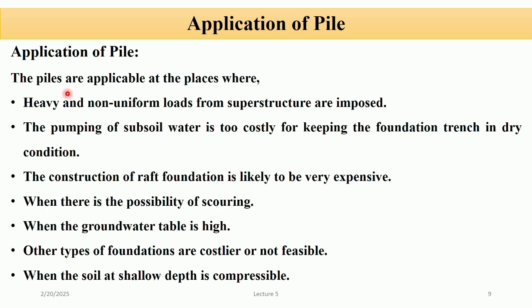Application of piles. Piles are applicable at places where the structure has heavy or uneven loads that need deep foundation; where removing groundwater to keep the foundation dry is too expensive; where the construction of a raft foundation is very expensive; where there is a possibility of scouring, meaning the erosion of soil; when the groundwater table is high and other types of foundation are costly and not feasible; and when the soil at shallow depth is compressible and not capable of supporting the structure. Then we provide the pile.